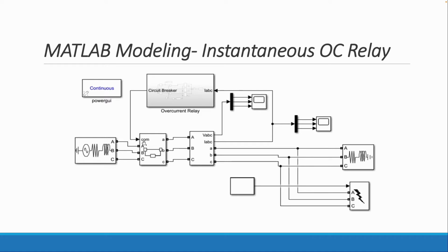To ensure that the breaker trips even if one of the phases is faulty, the relay block uses a relational operator, SR flip-flops, and AND logic. Basically, the current values from each of the three phases are considered when this relay is operating, and with the aid of the RMS blocks, the value of the current is determined.